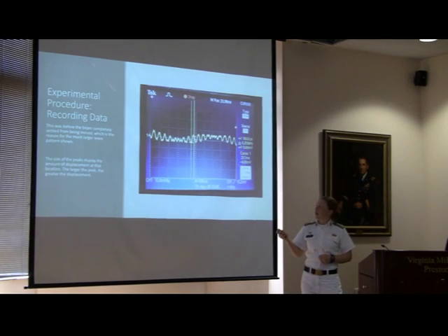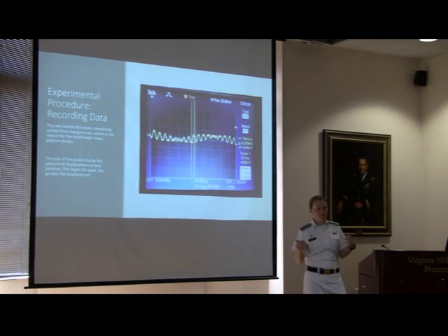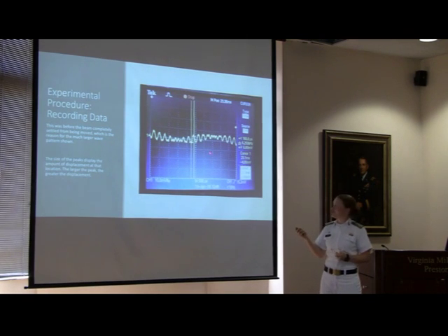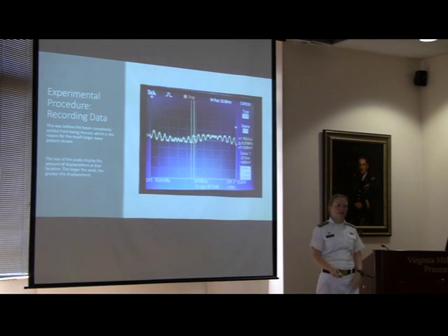So this is not a great picture because it shows a little bit of outside noise coming in from the beam. What happened here was I actually walked past the beam right before taking this picture and set it vibrating a little bit more than it was supposed to be. So that's why this larger wave is coming through here. The solution to that would be to just let it settle again before I take the measurement, and not walk so close to the beam next time.